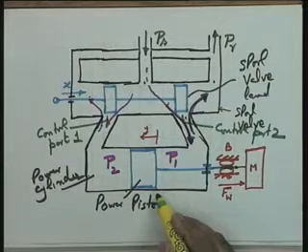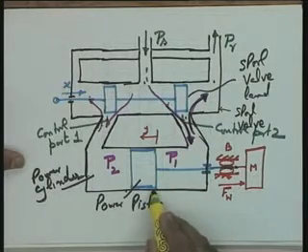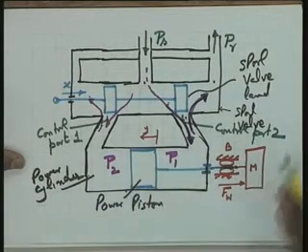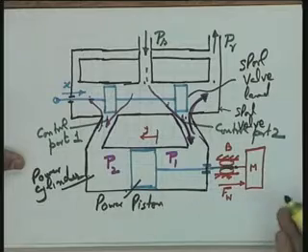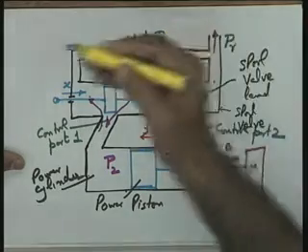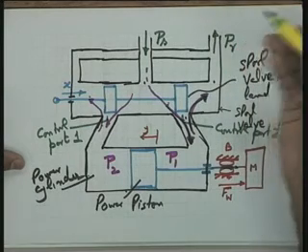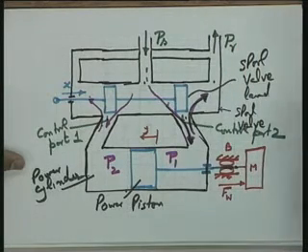What is that pressure equal to? Please note that this pressure is equal to as demanded by your load, because the force produced is going to be area into that pressure. So, it means the supply pressure is also a design variable. You have to design that value appropriately. What are the requirements?